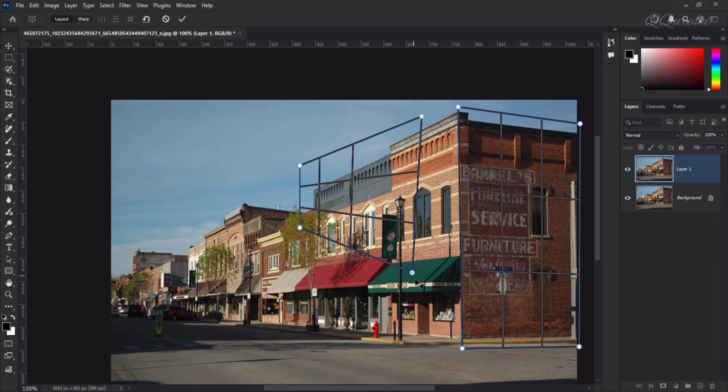Here we have to attach the 2 grids together. Grab it right here, and drag it over, but don't hold the Shift key. Just drag it over, until you see a blue line up here pin to pin, it will match it. And, as soon as you release the mouse button, both of them will be attached to each other.